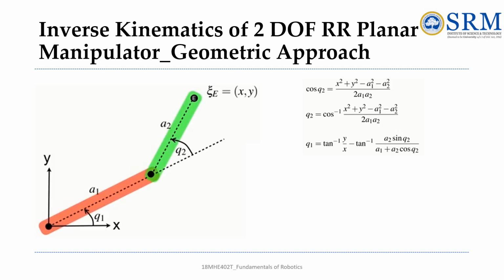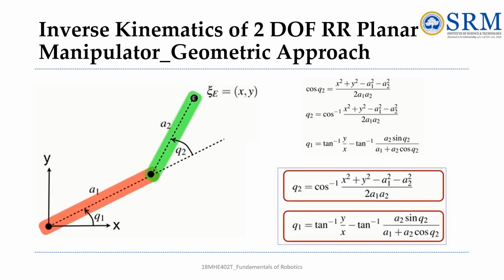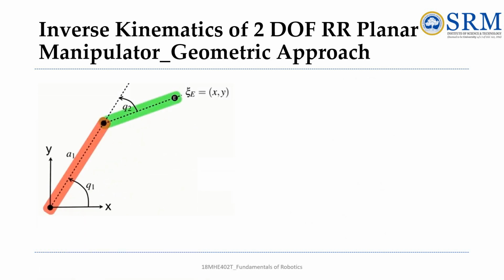now we have got q1 and q2, the angles, by using the links a1 and a2. Now the other approach is, if the link is twisted in this way, you will get q2. If link 2, that is a2, is twisted on the other side, you will get the other solution, right? So we are going to see the second approach, by the geometric method or inspection method, where link 2 can be moved to whichever side.